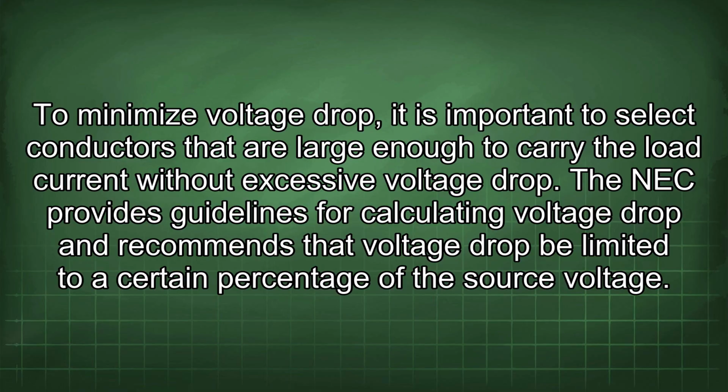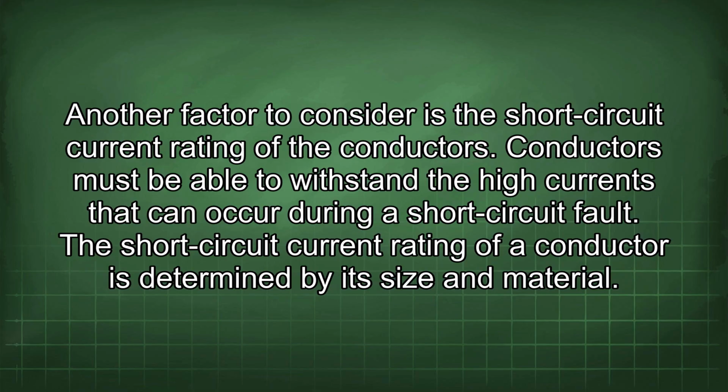The NEC provides guidelines for calculating voltage drop and recommends that voltage drop be limited to a certain percentage of the source voltage. Another factor to consider is the short circuit current rating of the conductors. Conductors must be able to withstand the high currents that can occur during a short circuit fault.